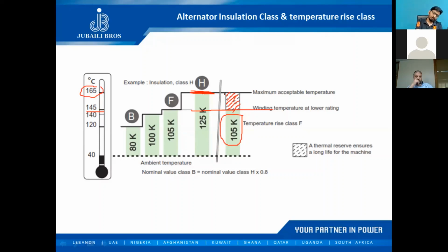However, if I want to drive at 160 kilometers per hour every day, what if I buy a supercar and do that? Do I shorten its life? Not at all, because it's designed to reach much higher speeds. So 160 is nothing. I hope this analogy makes it clear. It's the same idea here. Temperature rise class depends on how we load our alternator.